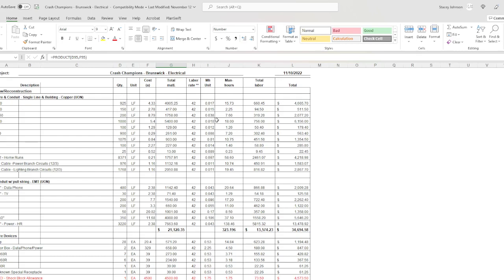So use a cost book because you want to be accurate. You don't want to go by, I've been doing this for 30 years, it's going to cost this much, because you could be shorting yourself. And you could be overcharging the client and you won't win. And so by using a cost book, you're in line with industry standard. You can test the waters: if you've been to 3 GCs, send them all the lowest, or send each one, tweak it a little, every estimate, whatever. But always try to go by industry standard, okay? You'll always be guaranteed to be really close in the competitive portion.